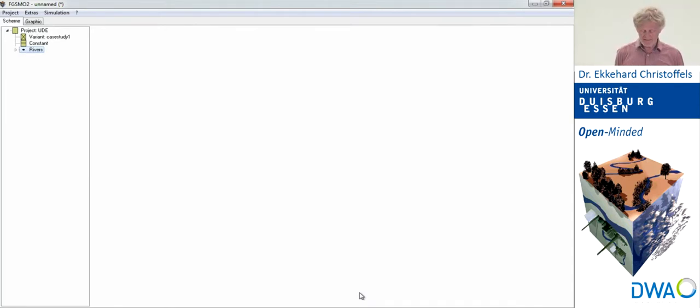Now you can see that our river number 1 is generated. A click on the small triangle to the left of the river name leads us to 4 more folders: the profiles, regions, sections and notes. In general, you can activate or deactivate subfolders by clicking on the small triangles. For the simulation, it is essential to link the cross-section of the river with the model. We do this by pressing the Profiles button and right-clicking Append a placeholder for the profiles.